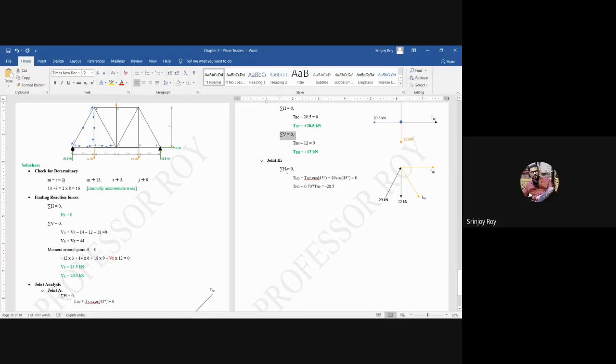So the summation of V should also be 0. तो यहाँ पर vertical forces क्या क्या है बताओ? Which direction are you going to take positive? ये पहले बता दो. In which direction will you take actually the positive direction? The upward direction. So which force is actually in the upward direction? कौन सा force? This force is actually in the upward direction, right? ये वाला, 29. इसका जो वर्टिकल कंपोनेंट होगा यह हम लोग कंसीडर करेंगे. इसका साइन कंपोनेंट क्या है? 29 sin 45, that's what.